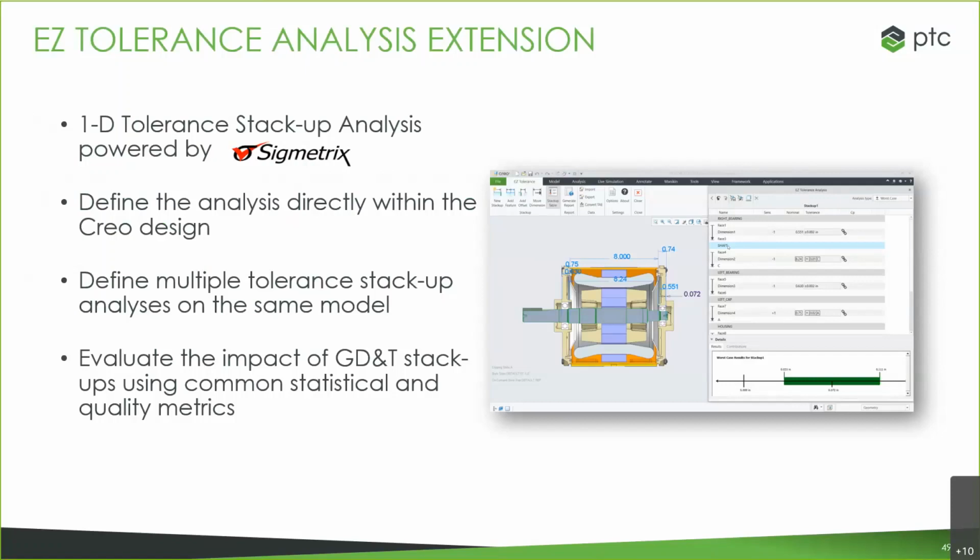With this change, we've done a lot to update the look and the feel of the tool, made the user interface easier and faster to make these dimensional stack-ups. With those, you can define multiple stack-up analyses per model, and we can evaluate many of the impacts from those studies to look into things like statistical results, defects, worst-case scenarios, RSS.